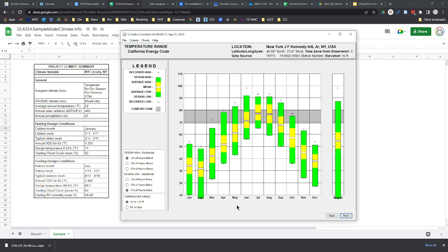Okay, so what I'm seeing here is, definitely January, February, March are heating seasons because there's no temperature ever that gets into the comfort zone. November, December also. I'm thinking definitely October. I mean, all these that have the averages are probably heating seasons. But this is subjective. You can interpret this however you want as long as it makes sense. But from this, we would say we're going to be thinking about heating in these months and cooling in these months. Okay, that's the first thing.